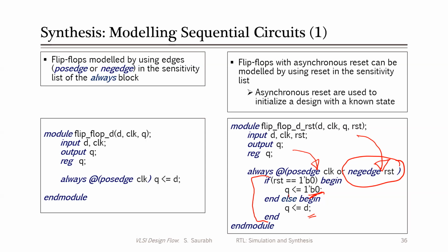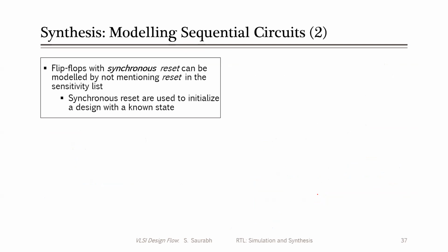Now, what is a synchronous reset flip-flop? Flip-flops with synchronous reset can be modeled by not mentioning reset in the sensitivity list. So what is the difference between a synchronous reset flip-flop and an asynchronous reset flip-flop? Can anyone tell?